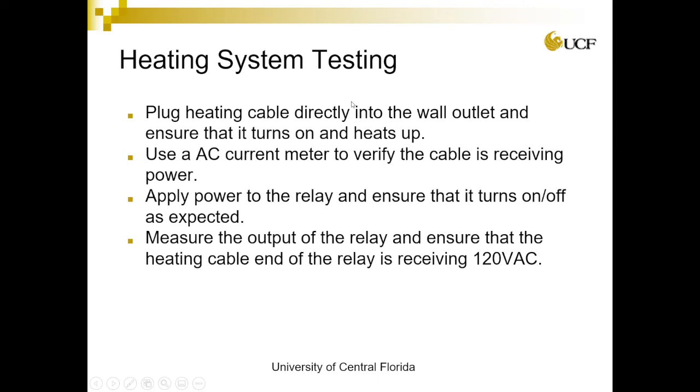To test the heating system, we intend on plugging the cable directly into the wall, maybe through an extension cord or something like that, and just make sure that it's actually turning on. To ensure that it's turning on, we're going to use an AC current meter around the cable and just ensure that we're actually getting power to it.